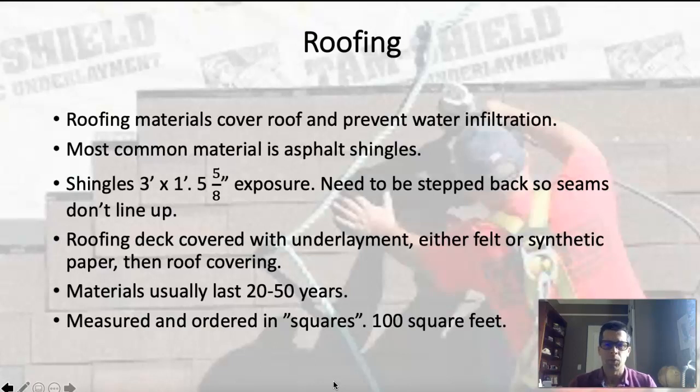But when we're measuring the roof, we're on a diagonal plane. So the way we would measure that is we would measure a rectangle at a pitch, measure one side of that. Say that's 40 feet long and it's 22 feet wide. We would multiply those together and get one side of the roof. And then if it's just a gable, we could double that and get the other side of the roof.